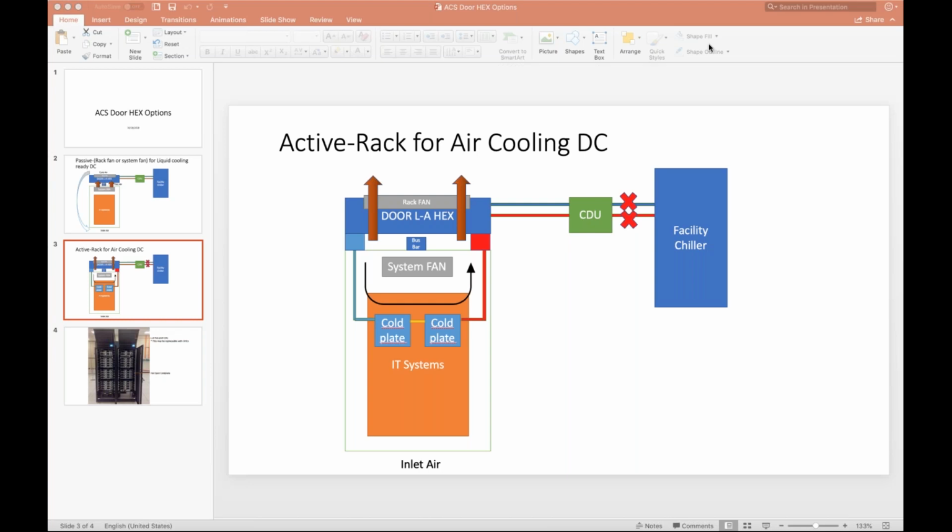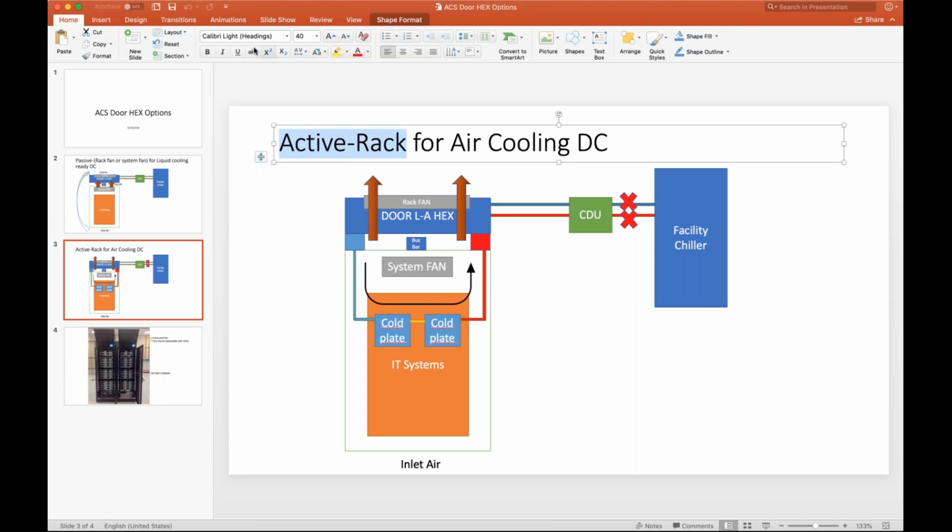Agreed, the same here. We do the same thing. And of course, again, you can combine the things, but the rear door has nothing to do with the cold plate systems. It's just they need both chilled water. But that's the only thing they have in common. And to clarify, for this active rack solution, if this did exist, the rear doors would need a pumping solution integrated. Normally, rear doors have no pumping system, so that would be one major difference. Agreed.